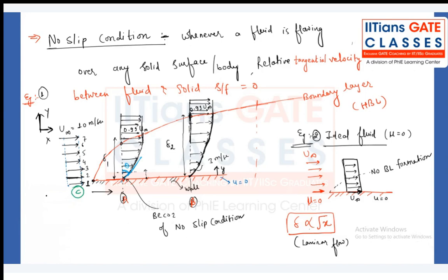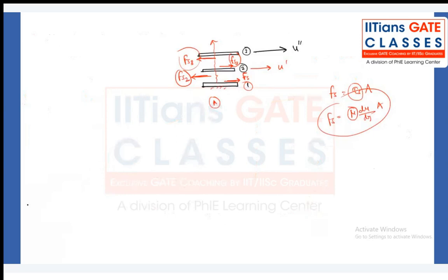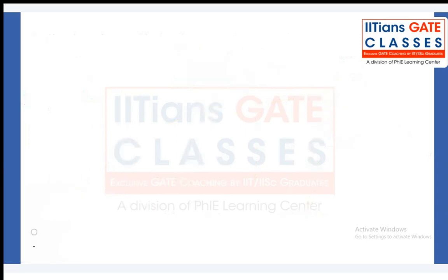So now you get to know that because of the property of a messenger, the first particle is messaging to the second particle, hello, please slow down. The second particle is saying to the third particle, please slow down. That's how the velocity gradient exists, and there will certainly be some narrow region near the solid wall where this velocity gradient exists. That narrow region will be called the boundary layer. So note down two definitions, which are very important. Boundary layer.